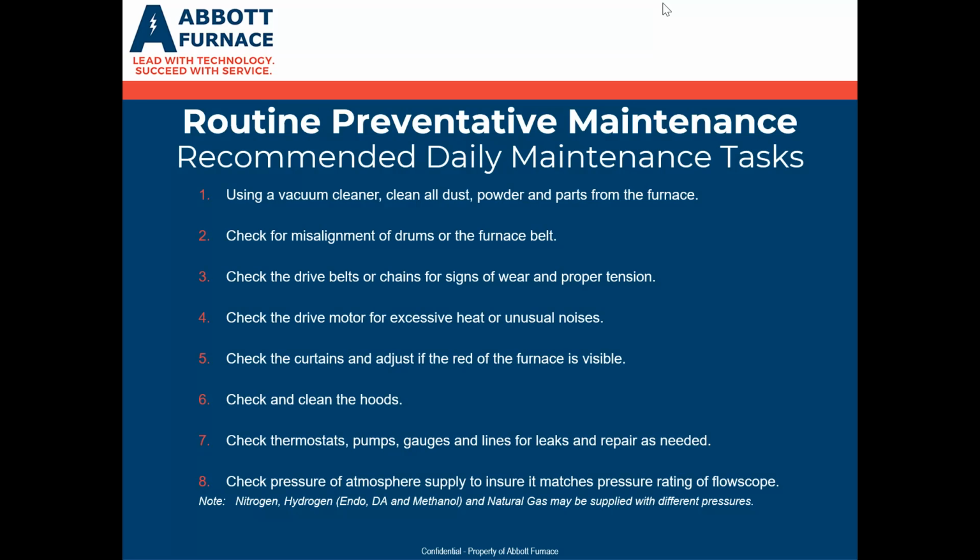One good check you can do is when you go to the back of the furnace, you can look through the rear of the curtain box. And if you actually do see the red up in the high heat section or in there, you know your curtains do need adjusted. Or if there could be wear in them from your different part sizes, it's very important to keep them up